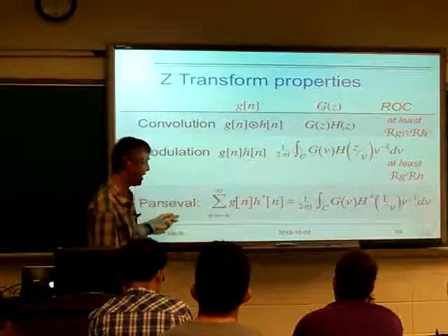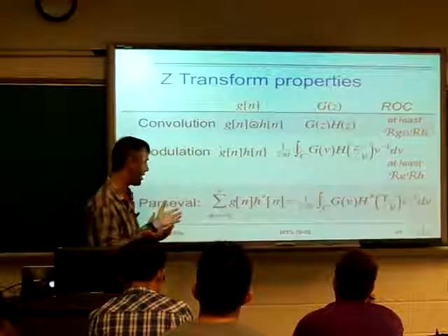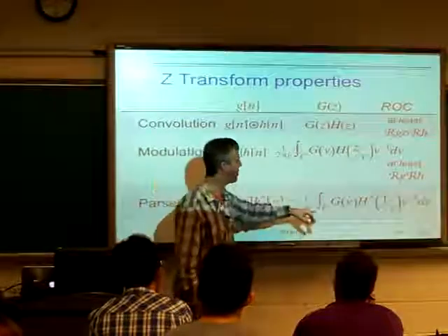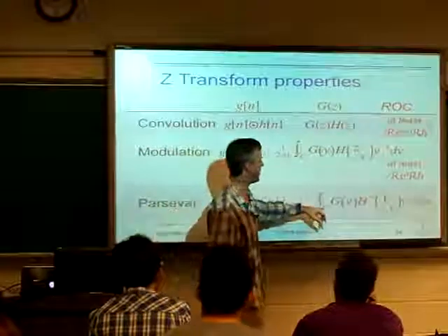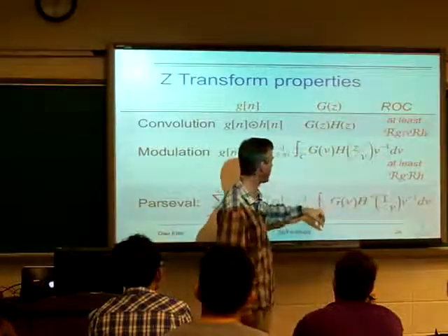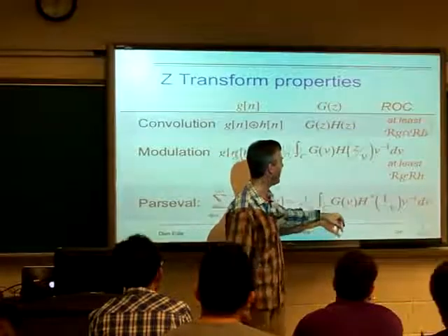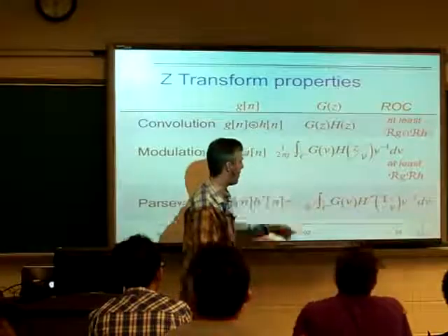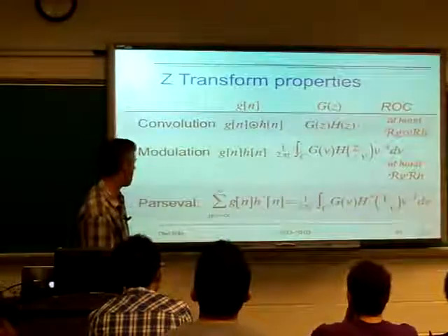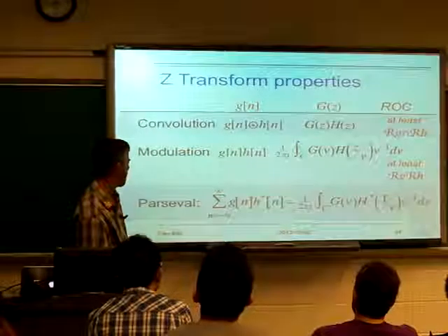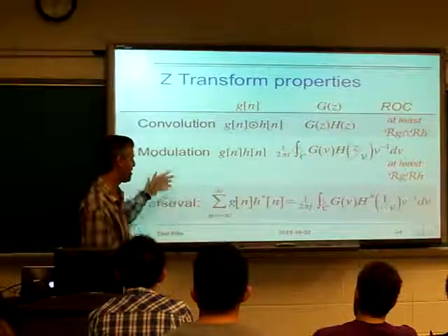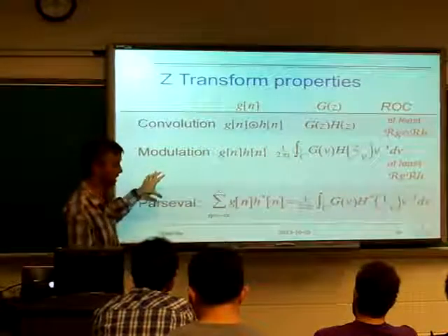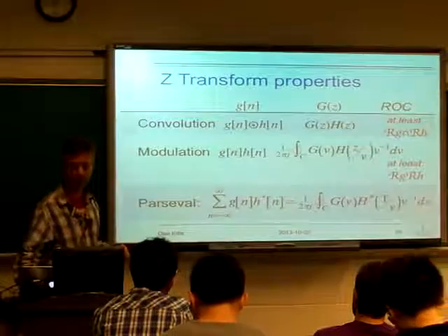And then Parseval's relation, which said that the sum of the magnitude squared in the time domain was the sum of the magnitude squared in the frequency domain, generalized to two sequences. That also works here, but again, the sum over all frequencies becomes a contour integral in the Z plane, and then instead of being a function of Z, it's just a constant here. It's basically the same expression, but evaluated for a particular value of Z. These are not big payoffs. This stuff is much easier to think about in the Fourier domain, but it's just to show that it is properly generalized into the Z transform.